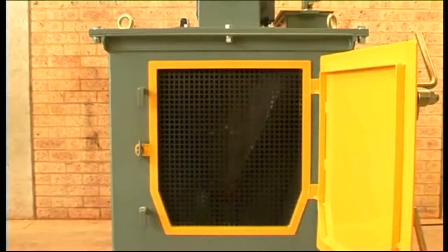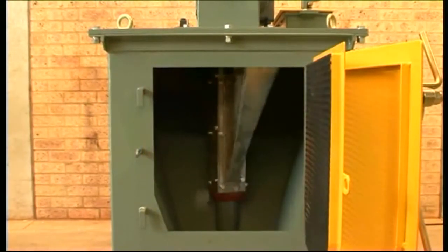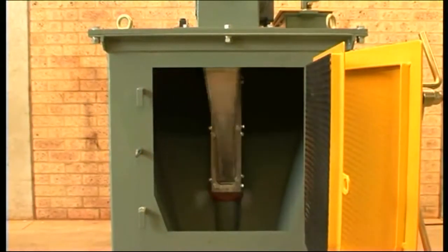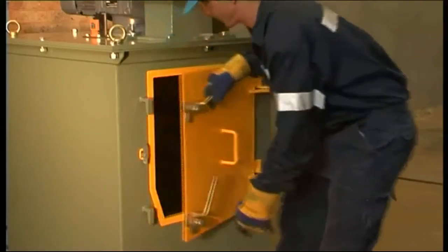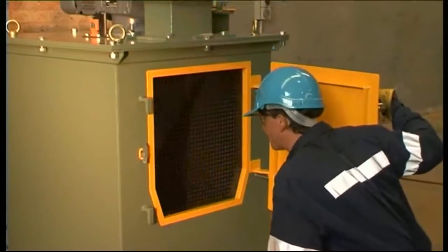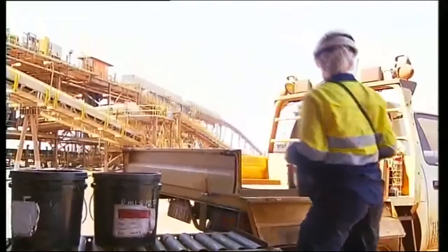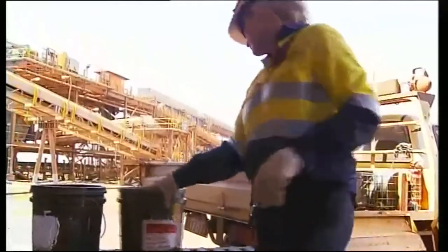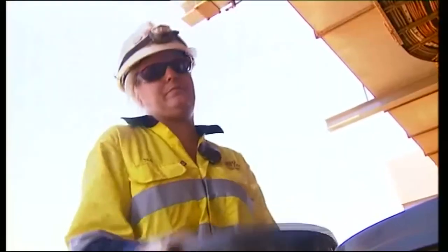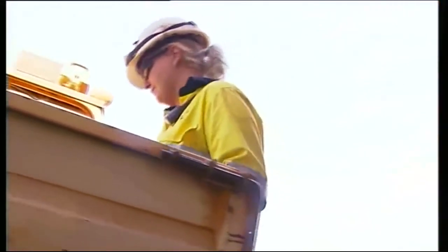A Vezin rotary sampler can be used in secondary, tertiary or even quaternary sampling. The technique employs radial cutters that rotate through the entire falling ore stream. Each cutter collects samples as it passes through the ore stream. The cutter must pass perpendicular to the sample stream, and it must pass a sufficient number of times to ensure a representative sample is taken. This process of sampling and subsampling is repeated until a representative sample reaches a weight manageable to an operator. Final samples range from 5 to 10 kilograms.